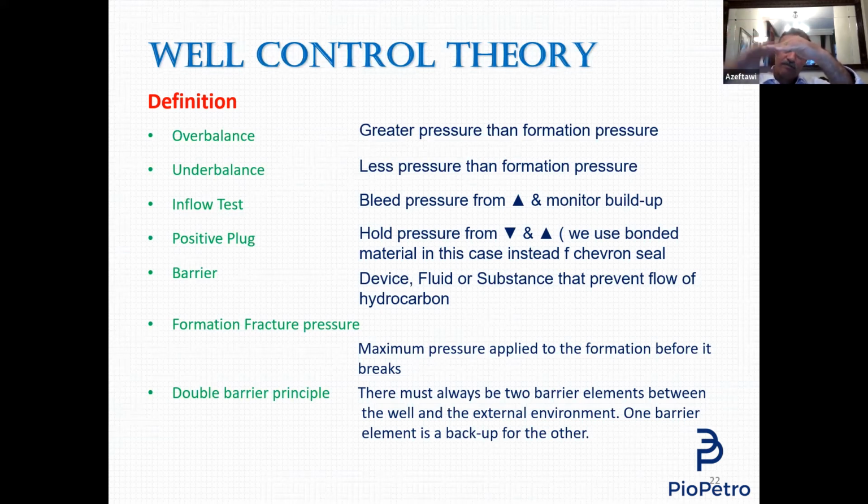Now, this swab valve is closed. I bleed off the pressure above it till it is zero. Now I can disconnect my equipment and leave.